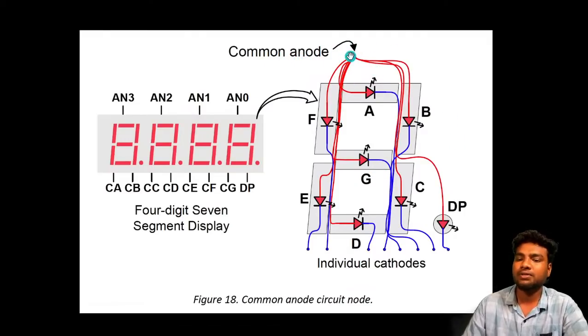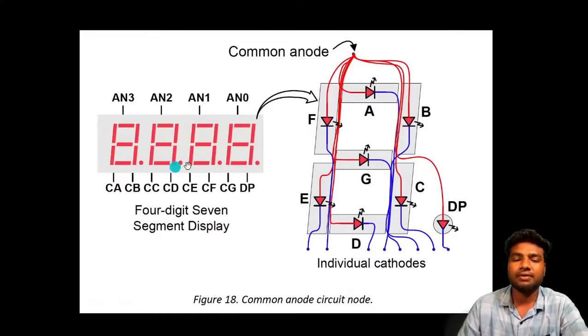Why are we using it? If you have a lot of seven segments, you can see in this example, it has a 4 seven-segment display. So I want to use one particular one. So this is the anode, and these are actually the cathodes. If you want the common anode, the anode pin is for choosing the seven segment.